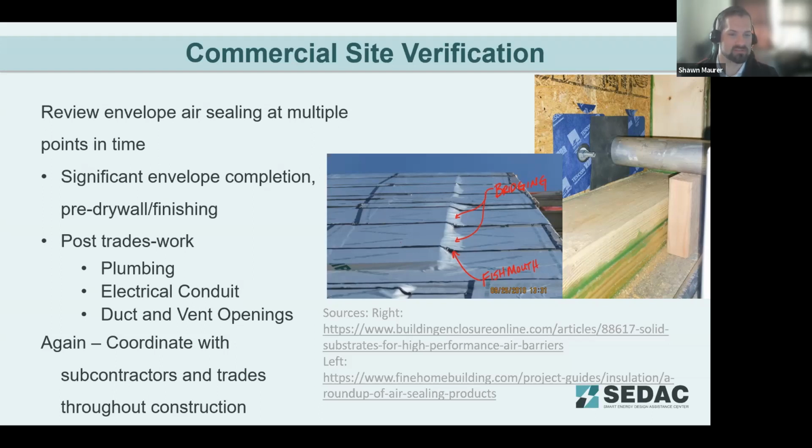And the fish mouthing is where that air pocket doesn't seal between the different sheets because there's not a hard surface behind it to seal to. And so it then leaves an open gap in the air barrier there. So that's the bridging it's talking about. There's overstretching of that insulation, or that wrap, where it doesn't follow the actual contour of the building.